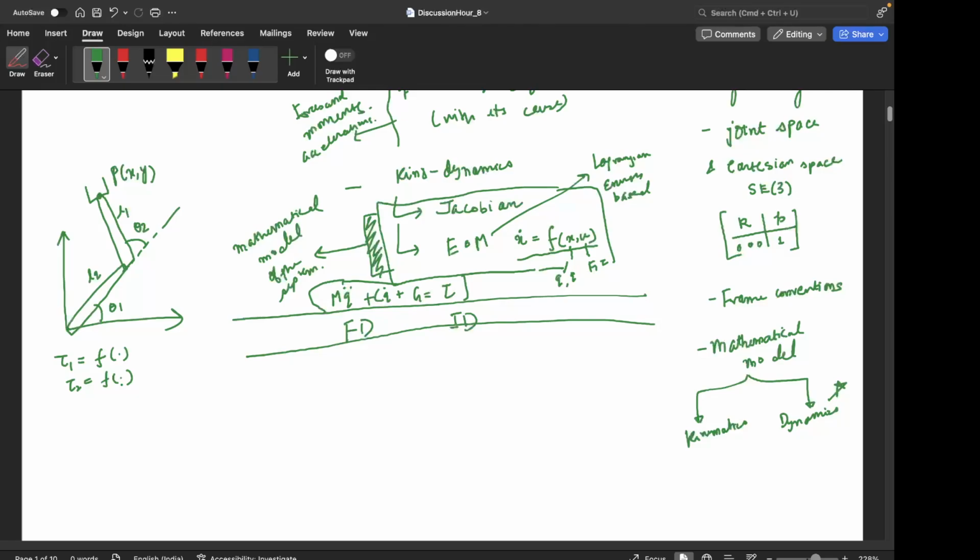So relating the accelerations and velocities of the joints to the joint torques. And if I say that this much torque has to be generated, or is being applied on the end effector, then in a certain configuration you can tell me what would be the accelerations of each of the joints. And if I say that the force is being applied for a certain time, then you can integrate those accelerations to find out the velocities and again the positions. So basically at any instant you can analyze the kinematics and dynamics of any system.